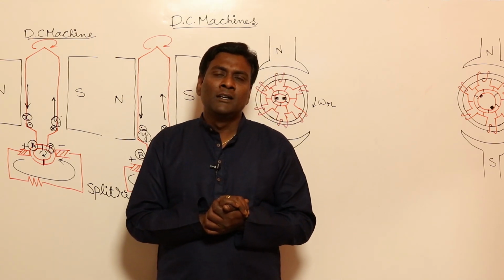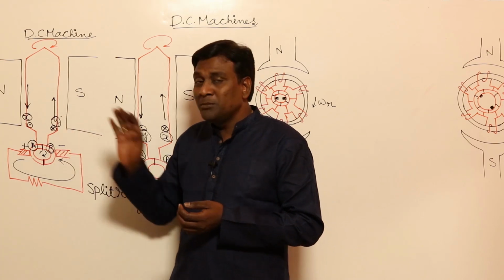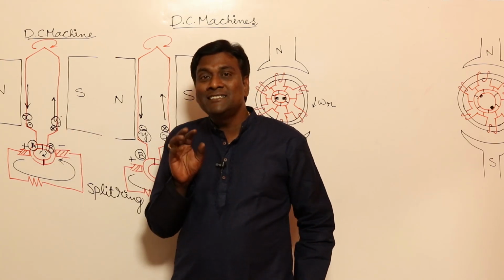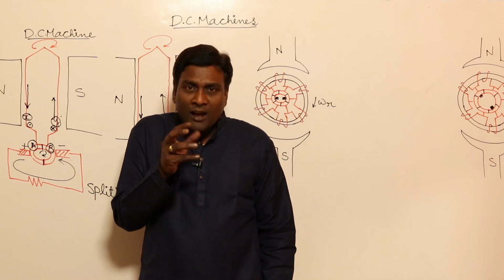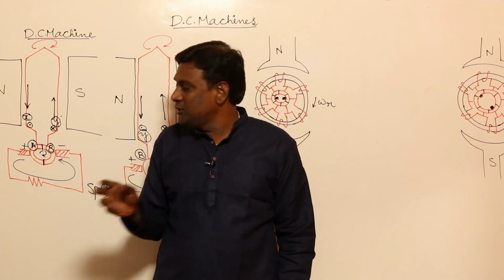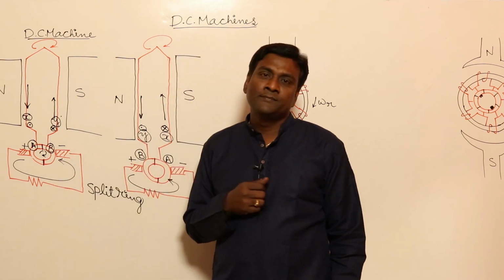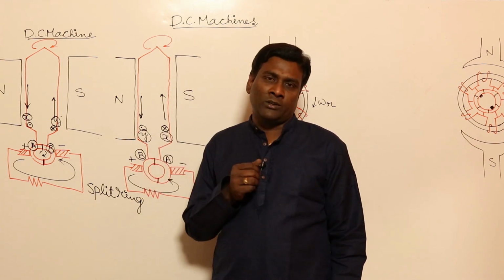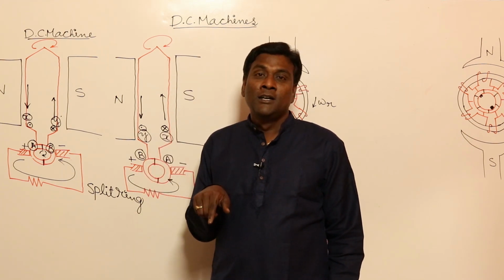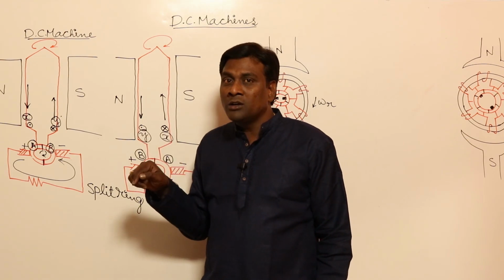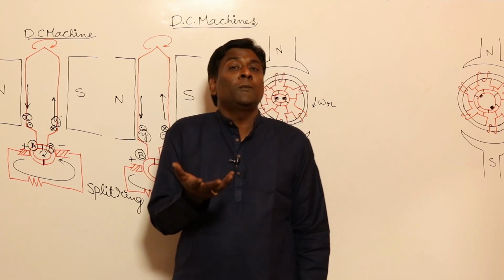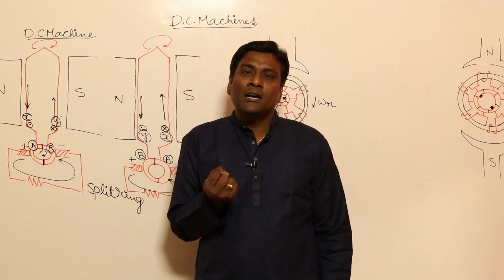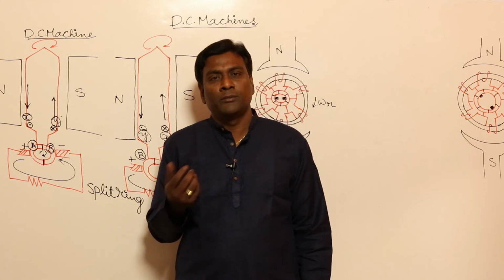Now in a DC machine, what is the commutator? It's a mechanical rectifier. So mechanically you have to rotate the rotor in order to get DC voltage. So in a DC machine, the armature should be in the rotor only. There is no other option because of the commutator. The moment the armature is in the rotor, centrifugal forces will be there and hard composition material is needed. Because of that, the cost of the DC machine is going to be more.